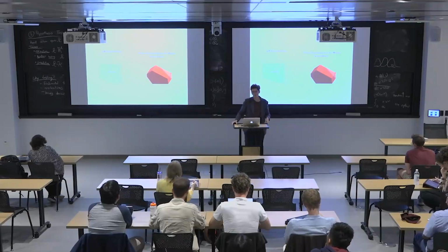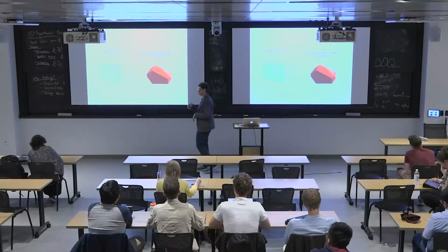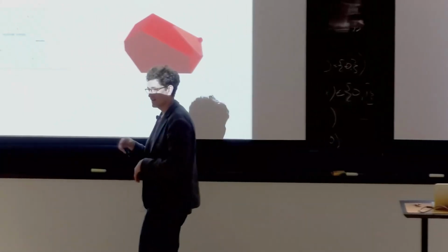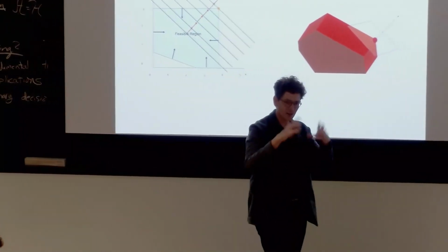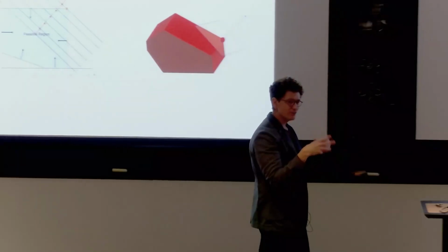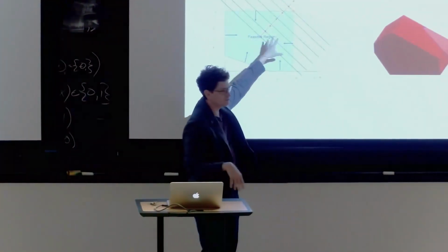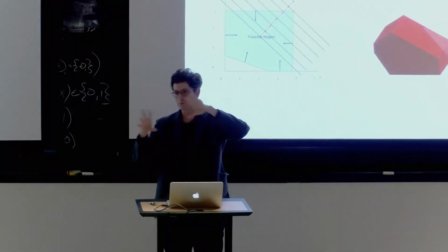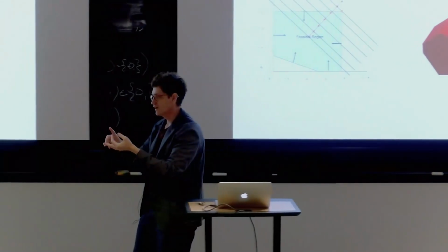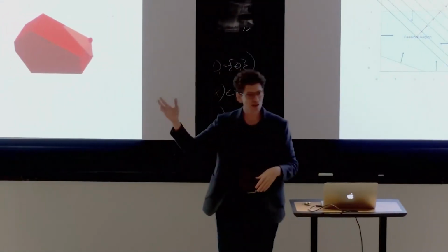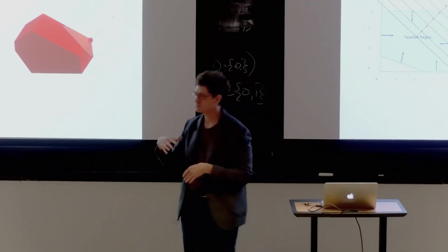So what we do is we write functional constraints for every generator, the cost of their electricity, how fast you can turn on the plant, how long the plant has to be off if you turn off the plant, because nuclear plants can't just turn on and off every second, right? You write all of these functional constraints, and you put it into this model, and then you have this feasible region, which is defined by what is available for fuel, wind, sun, etc. And you do a cost minimization procedure to find out what is the minimum cost system.